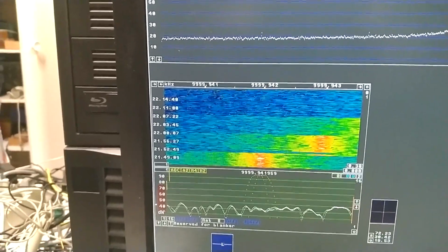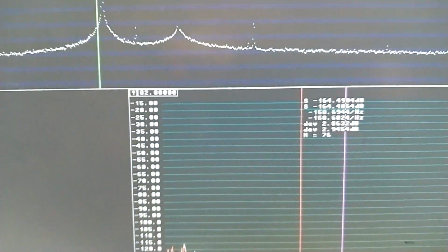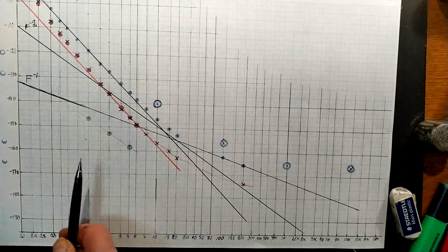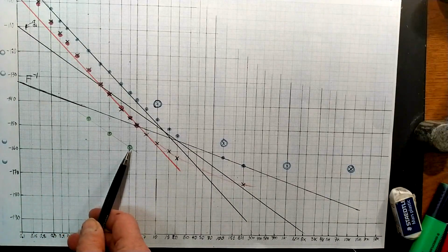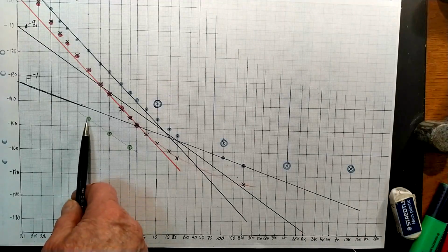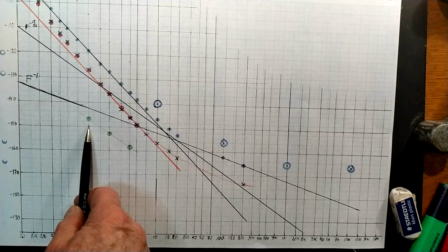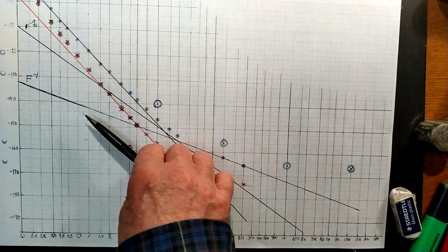And now I look at 4 Hz offset, and there I see minus 158.7. The noise, when I measure as a Q multiplier, comes like this. It's an F-2 noise, and this is AM noise plus phase noise. So phase noise only would be down here if it was an oscillator. But of course this line will depend very much on how much feedback there is.